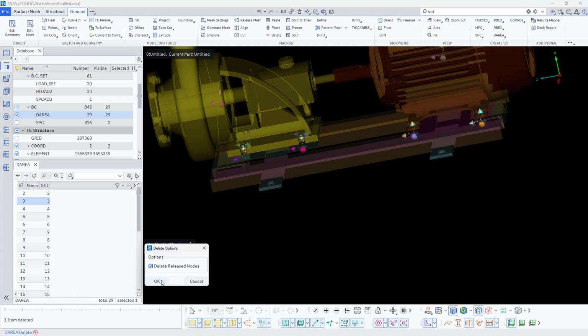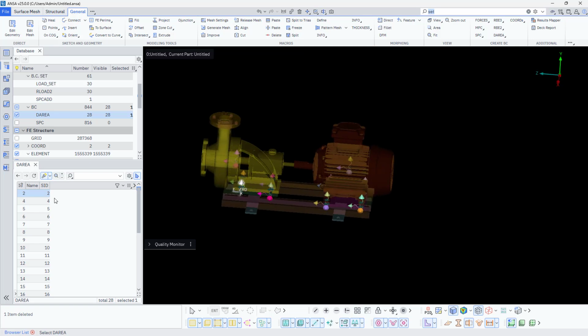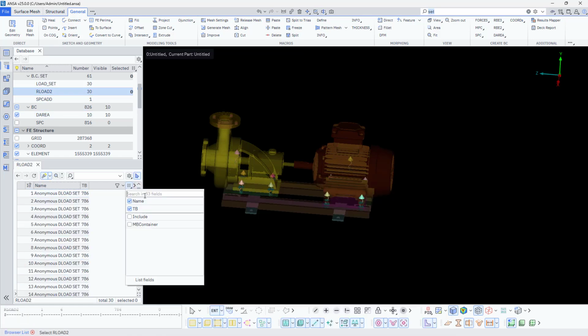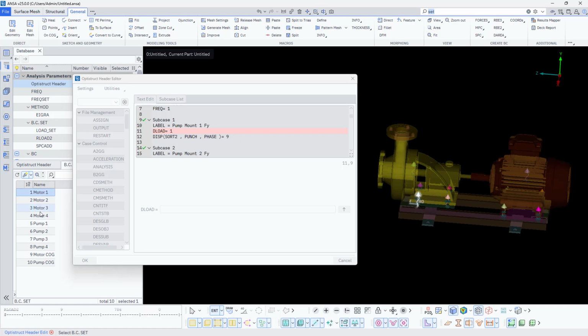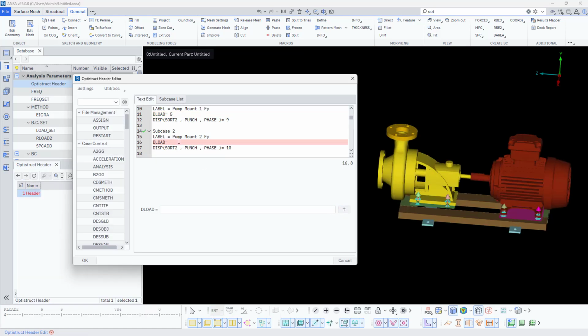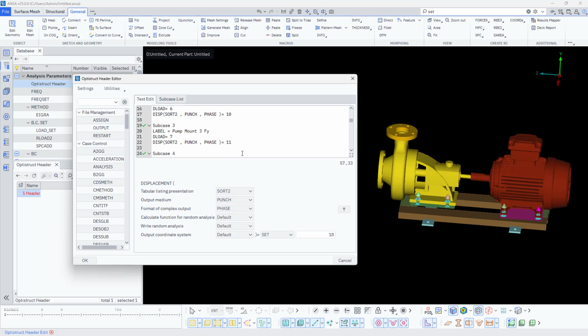In short, it is just an analysis which I'm doing here to show you how we can use this NVH analysis to optimize the component as per our requirement. You can see it is only along Y. I'll be changing the same. We have taken it for all the mounts, so I need to delete the F of X and F of Z subcases that I have done. Here I just need to call it again, so that is what I'm doing here. Similarly you can cross verify everything.